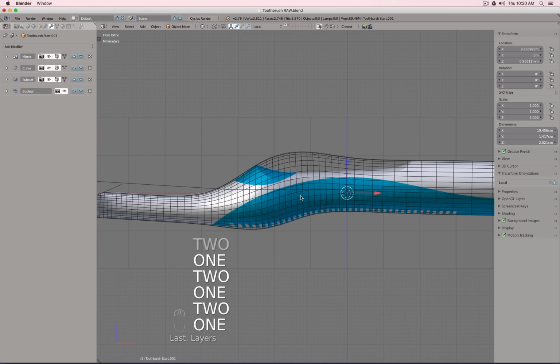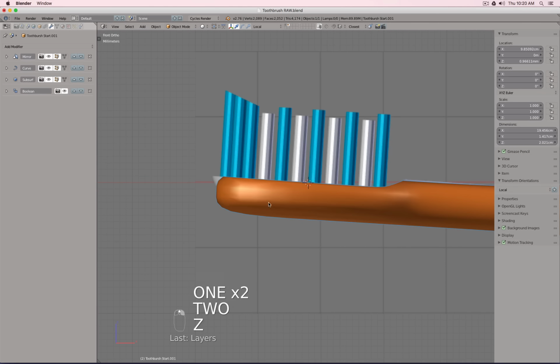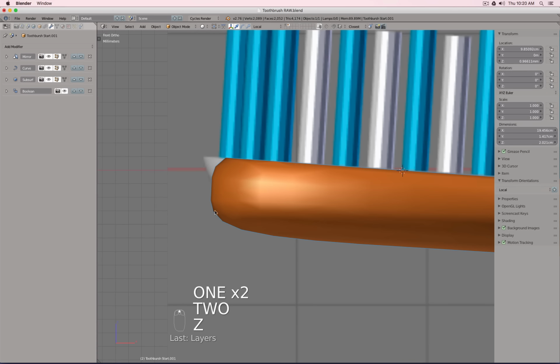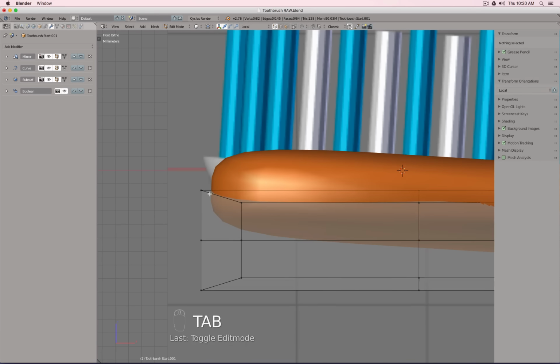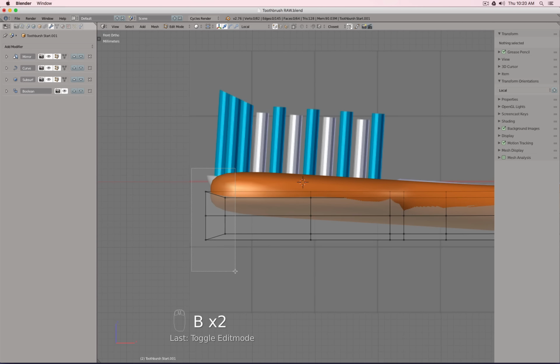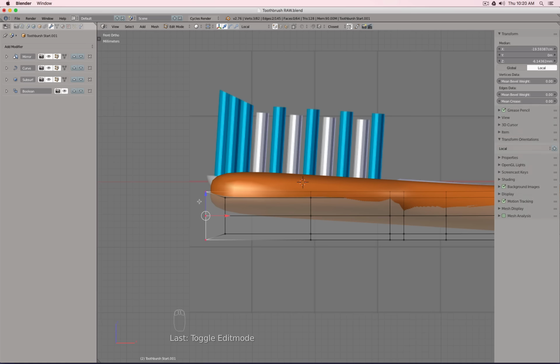Yeah, okay, well this is what we cut away, so not a big deal. So do I now like, for example, how this one goes flat down? So maybe I want to shear actually, let's say this part. So spacebar, shear, or shift, control, alt, S.